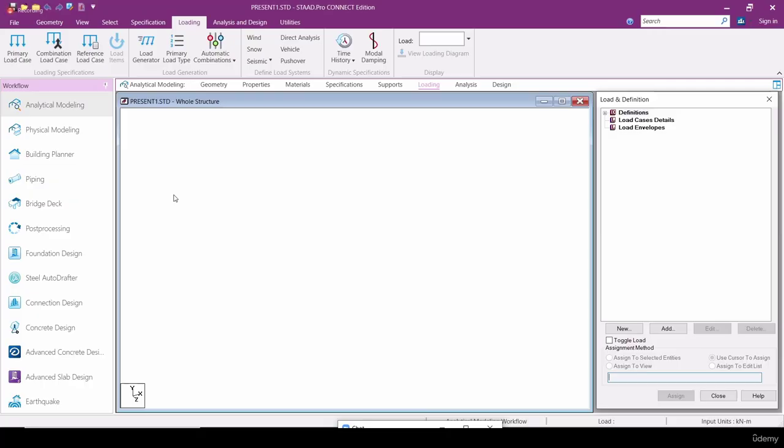If you apply a 1 kilonewton load on a particular beam, it shows how much the deflection will be. That is the spring constant K, generally denoted by K, in units of mm per load, or deflection per load. So for the calculation of spring constant, or anything where you don't want to use the load in a load combination, you have to use the reference load case here.